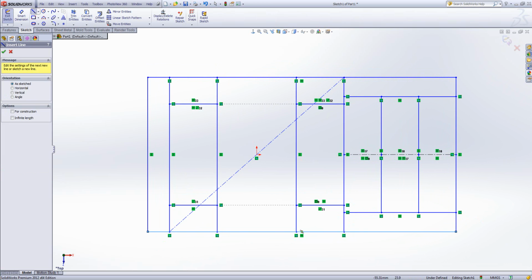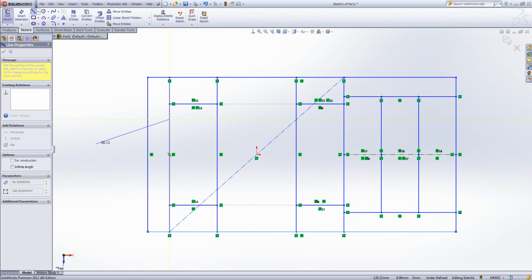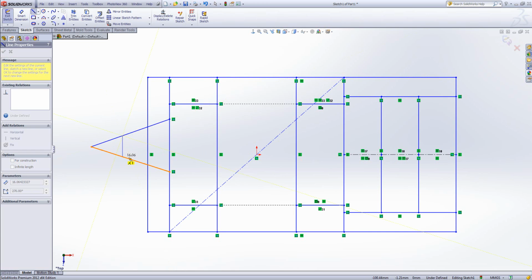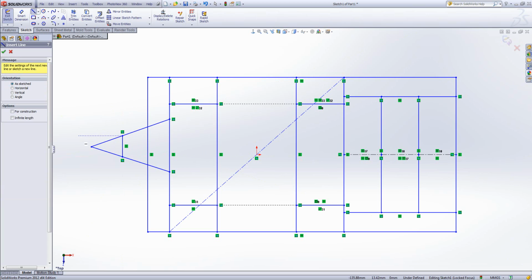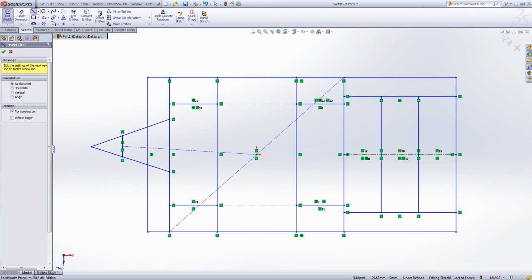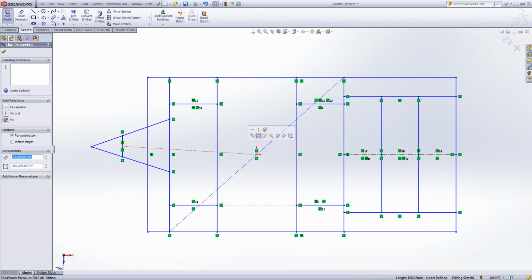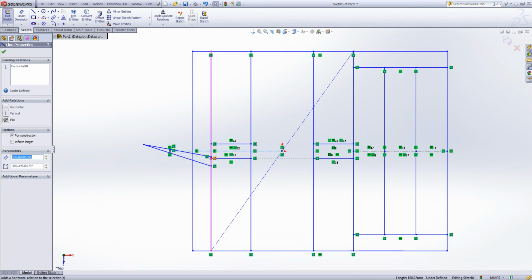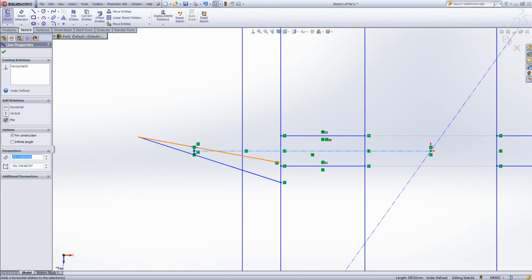So one of the last changes I'm going to do is just to add in a triangular section on this left hand side. And I've just added some simple sketch items in here along with a construction line to hold it in place. And again I'm going from the midpoint because it's very good at maintaining that symmetry. So if I make sure that this line stays horizontal, it should mean that the item will update nicely around the center with regards to this line.